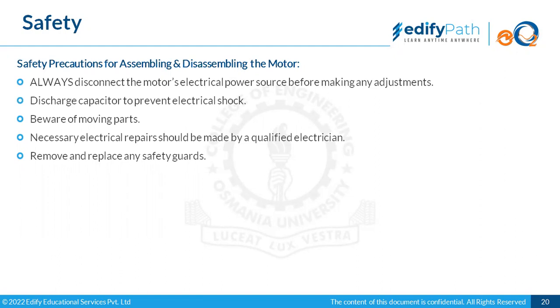Beware of moving parts. When we are attending to a running motor, we should always see that the belt portion and other portions are properly covered. Because if there is no proper guard on them, there could be an issue, or if we are crossing across the motor wearing loose clothes, they could be a cause of accidents. So we should take care of the moving parts, and be very careful when we are moving across the motors.